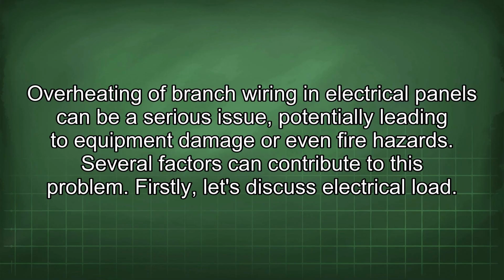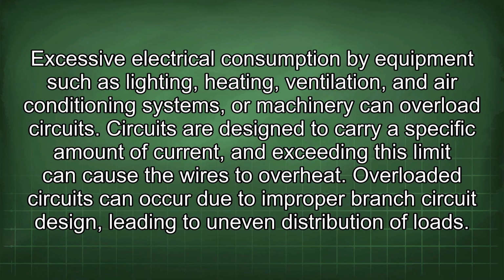Overheating of branch wiring in electrical panels can be a serious issue, potentially leading to equipment damage or even fire hazards. Several factors can contribute to this problem. Firstly, let's discuss electrical load. Excessive electrical consumption by equipment such as lighting, heating, ventilation, and air conditioning systems or machinery can overload circuits. Circuits are designed to carry a specific amount of current, and exceeding this limit can cause the wires to overheat. Overloaded circuits can occur due to improper branch circuit design, leading to uneven distribution of loads.